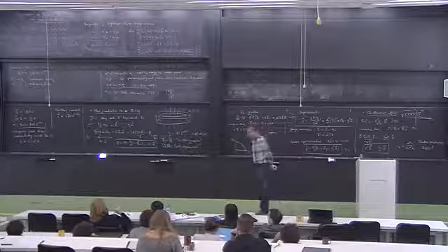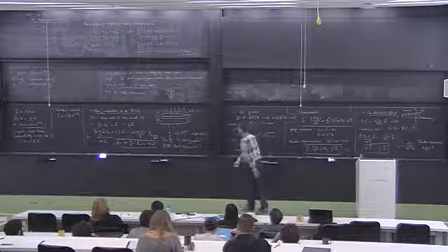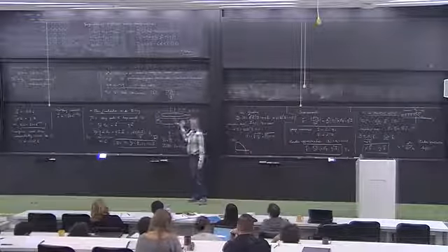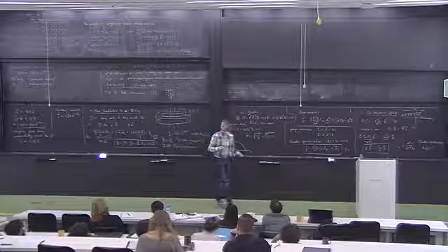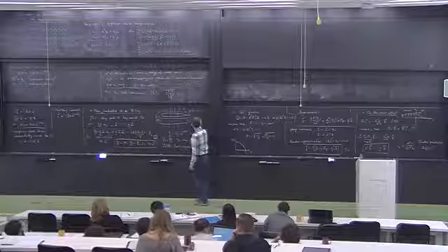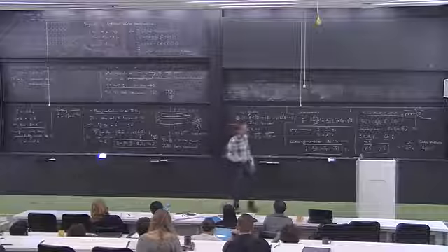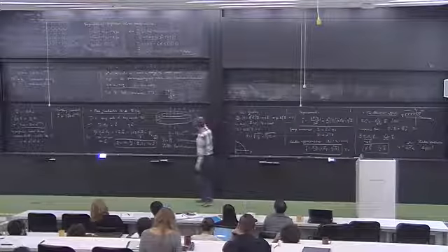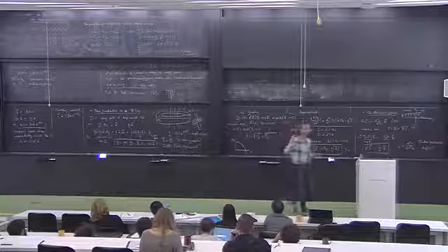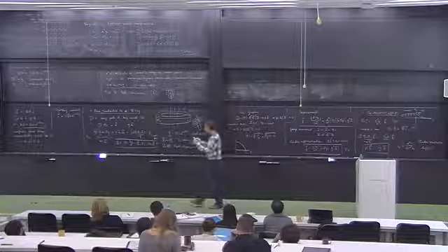Is the energy in there just that you've got a massive supercurrent flowing around that goes down? Yeah, so there are two types of energy. There's energy stored in your magnetic field, and there's energy stored in this supercurrent. In your MRI, you basically have a coil of a superconductor, and then you lie inside it, right? This coil is made out of fairly thin wire, which circulates this huge current. The nice thing is that once you set up a current in a superconductor, you don't have to maintain it. It just flows there. You don't have to pump it up.